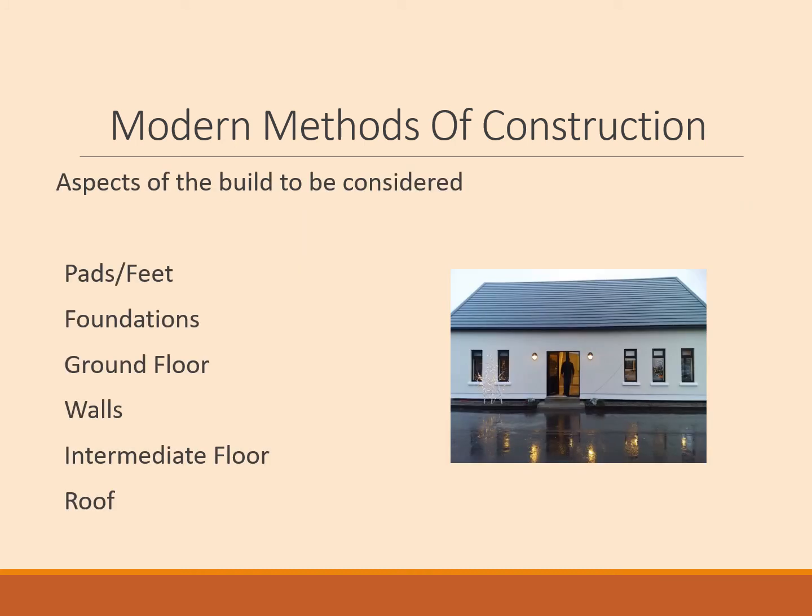Looking back at our modular built house, a steel-framed house such as this may be raised off the ground by legs and pads, which are bolted to the foundation. What is the fixing detail? What of the durability of the steel pads which are constantly exposed to the environment? Are the foundations adequate for the manner in which the building load is spread? What of the materials and workmanship of the floors, walls and roof?